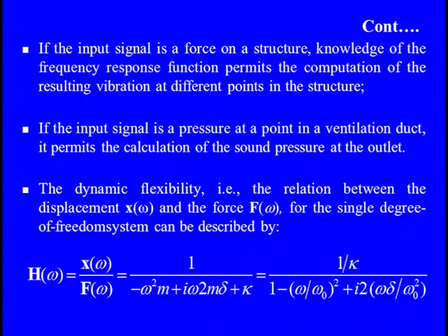So, with this concept, since we are basically discussing FRF here, if the input signal is force, this is one of the important things, what exactly your input signal is. If our input signal is force on a structure, the knowledge of the frequency response function simply permits the computation of the resulting vibration at different points in the structure. Because if we define the force, we know what the line of action or the point of action of the force is.